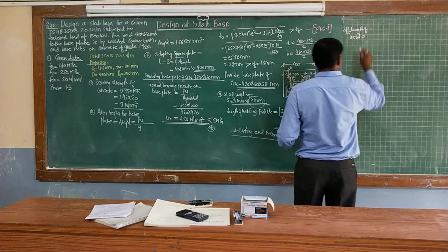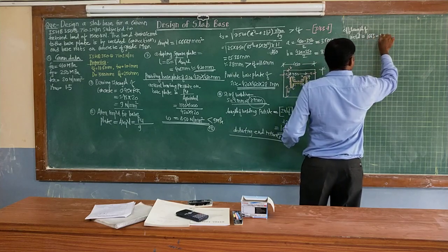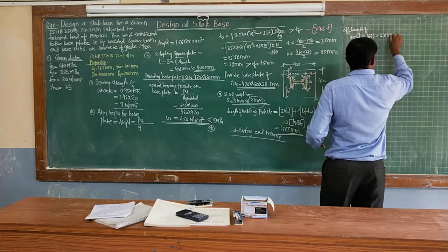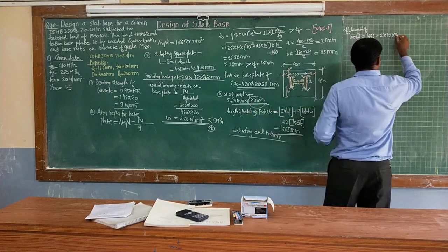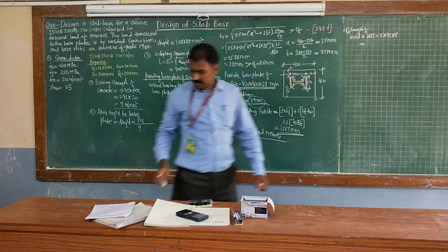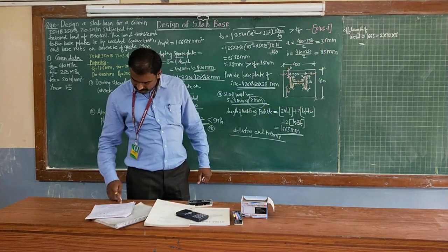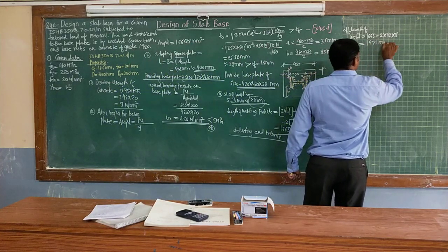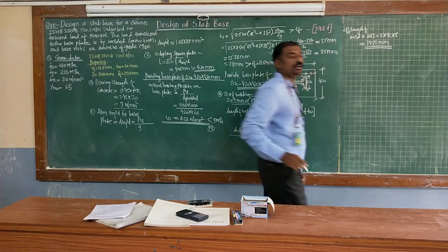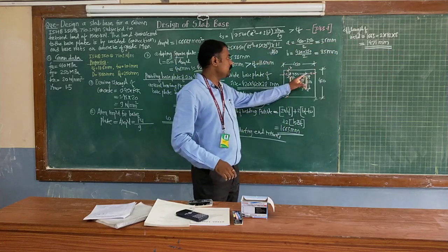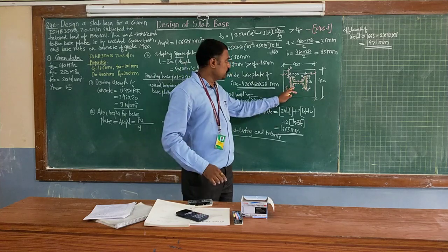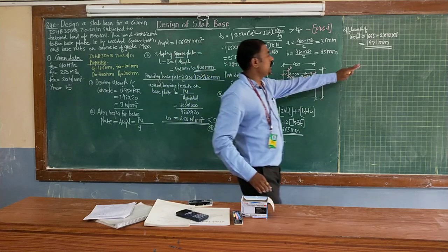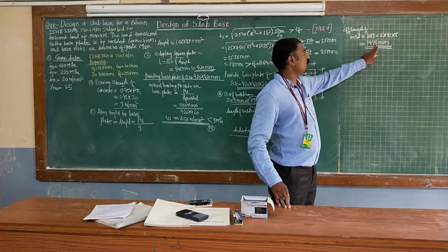is equal to 1663 minus 2 times size of welding, and size of welding adopted is 8 mm. So you are going to get the value exactly as 1471 mm. So this is the maximum or effective length of welding that is possible after deducting your end returns at every toe portion or junction at these locations. Correct? So final length of welding provided may be 1471 mm.